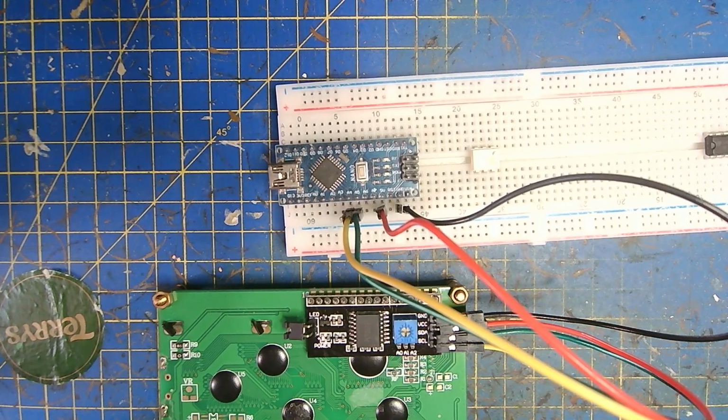If you connect to something else, it won't work. Other microcontrollers have their own pins. ESP32 uses pin 21 for SDA and 22 for SCL, and it allows those pins to be changed. The Arduino doesn't, so we're not going to. That's it initially. So what we're now going to do is power this up.